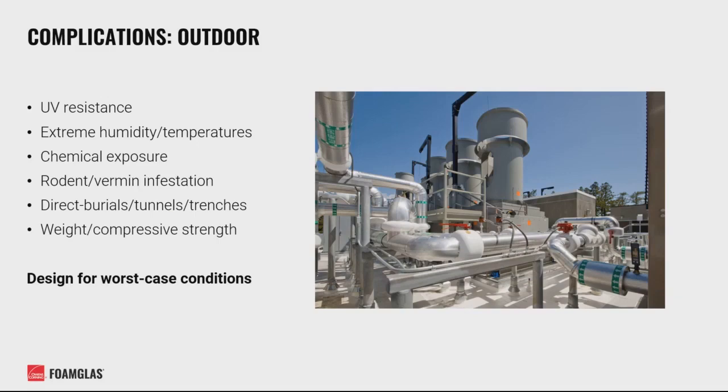Other important questions to ask may include, does your material withstand the burrowing activities of any local rodents or vermin? For direct buried systems, will materials withstand the compression load of soil backfill? If in high traffic areas, will materials withstand mechanical damage from pedestrian traffic or simply from the elements? Once again, the worst case conditions for your specific system should be determined and designed around.